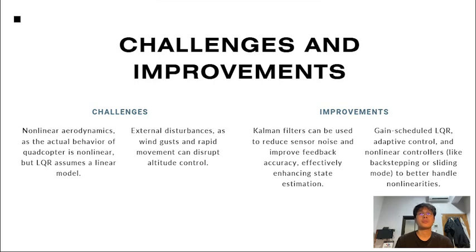So for the challenges and improvements, first the challenges. First is nonlinear aerodynamics, as the actual behavior of a quadcopter is nonlinear, but LQR assumes a linear model. Second is external disturbances, as wind gusts and rapid movement can disrupt altitude control.